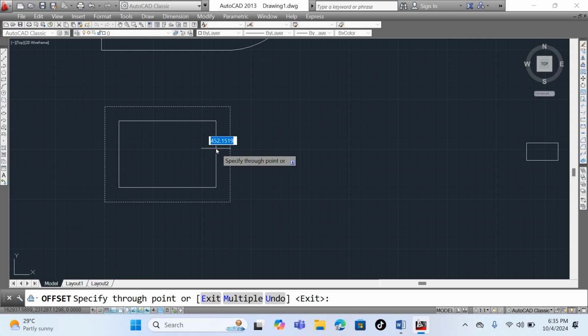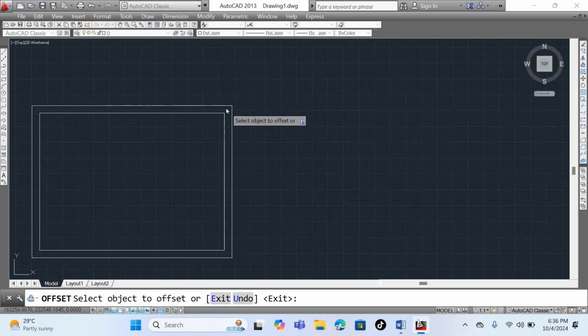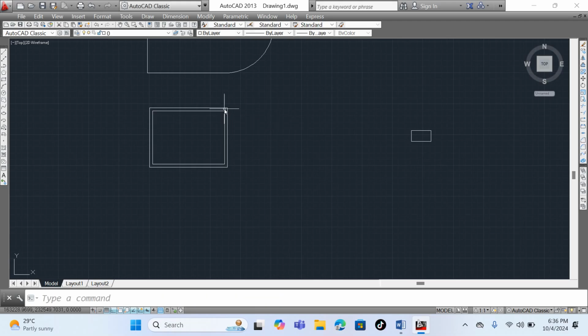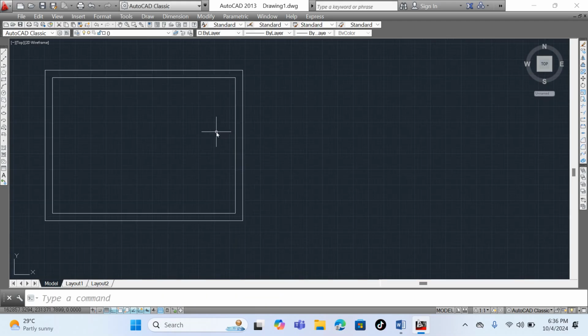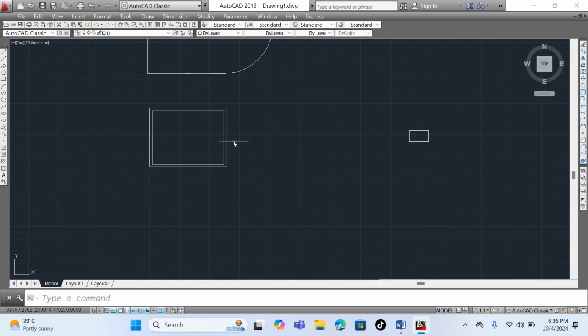Say if it was an external dimension of a room. So if you are now offsetting the wall, you take it inside and put the wall thickness. For example, we can use the wall thickness of 150. So it means we shall type 150 on our keyboard, and we press enter, giving us that, and we escape. Now I'm also going to show us to explode.